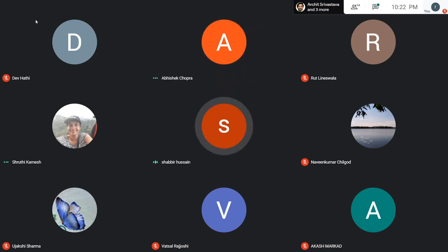Excuse me, just one more question, please. Sure, go ahead. Sir, for the non-overlapping grid, is it possible to actually apply DG? Because is it possible to counter with the flux function when the grids are not overlapping? For overlapping grids, we can play with the flux functions. If the grid is non-overlapping, how can we account for the numerical flux functions?